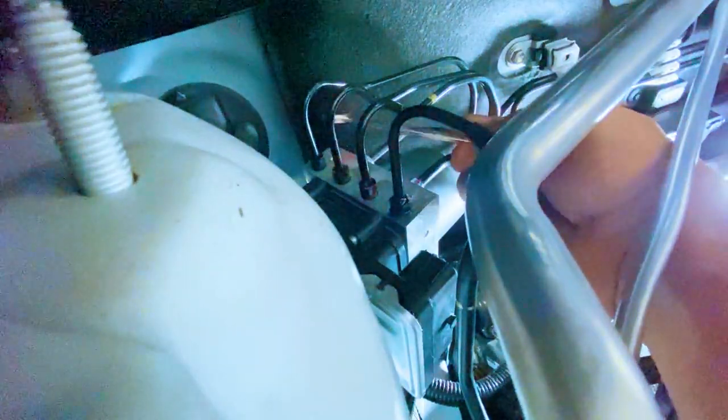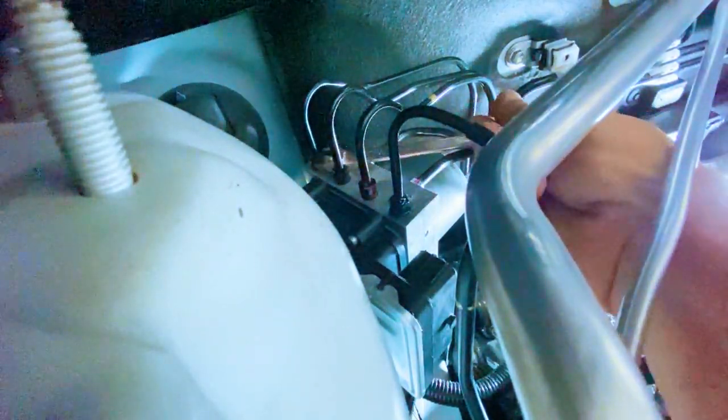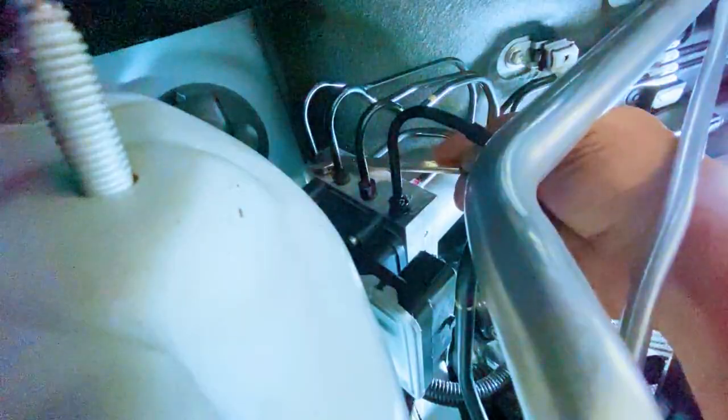When both codes are present, I would not immediately install a new brake actuator. First, I would verify the electrical system. Check the battery. Check the ABS power supply. Check the ground. Check the fuses. Check the connectors and terminals. Then check the wiring for an open circuit or short circuit. If all of these tests are good, the brake actuator assembly becomes the main suspect.